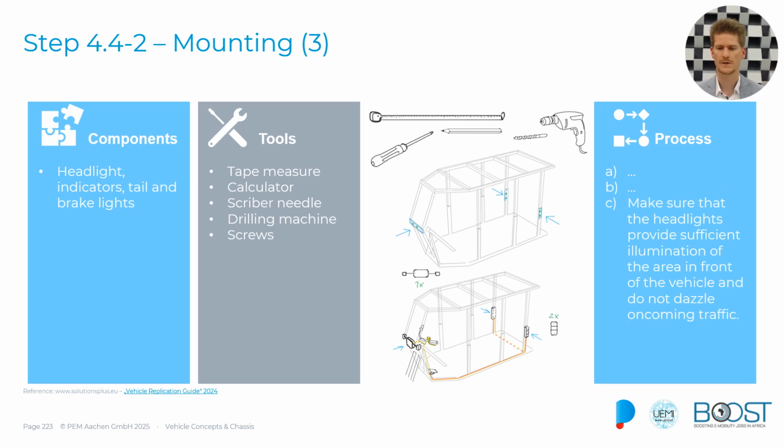At this point, you will then just check that the lights do all work. They do have a sufficient amount of light to be emitted, and just check that they will point in the right direction and the right angles, not to dazzle some oncoming vehicles.